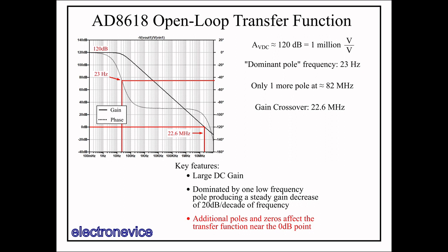Now that we've talked about open loop gain, we need to translate this into loop gain for an op-amp with a feedback network. The easiest way to demonstrate this is graphically, as the equations don't really provide much insight. So let's discuss how to extract the loop gain from a given op-amp circuit so we can extract it from some example circuits from LT-Spice.